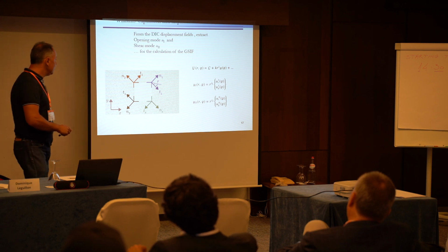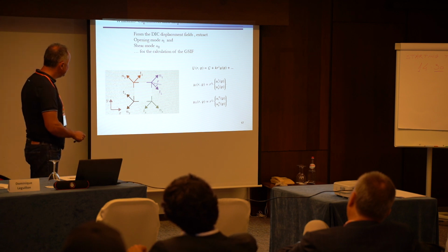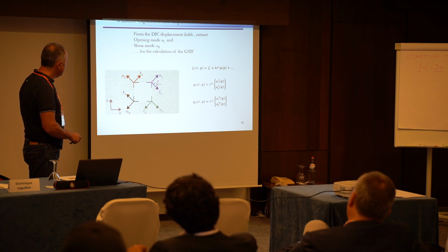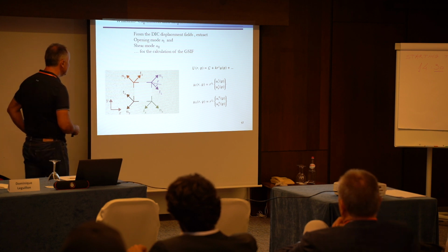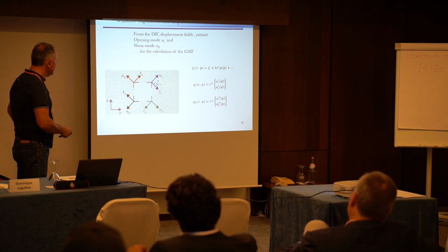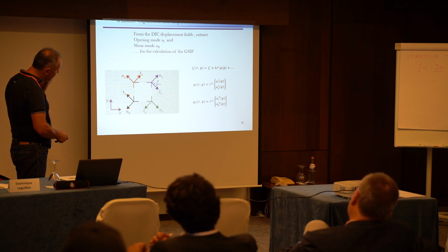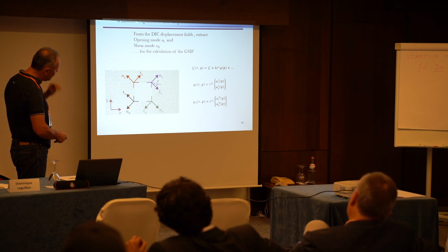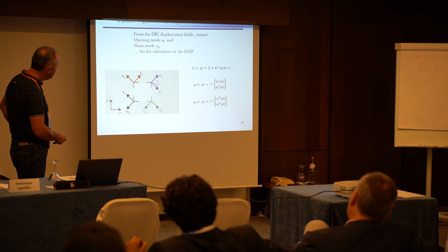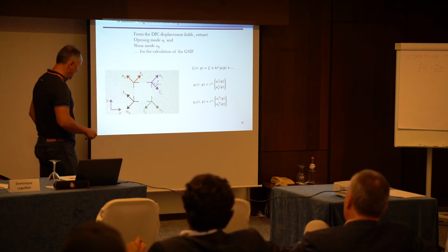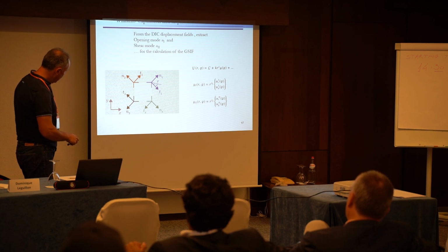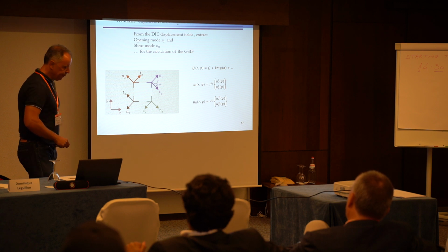So what do you define? You define the direction of the bisector and its perpendicular direction. From each corner, you can identify it more or less accurately. You define the distance R with respect to the notch tip and the angle phi, to make it distinct from theta. You do that for corners 1, 2, 3, and 4.